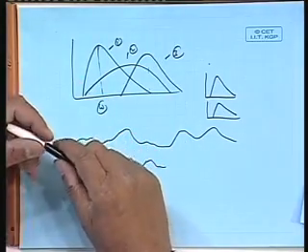If you take a particular location and wind is coming from a particular direction at a particular speed, waves will be random, but you would still expect the statistical quantity of waves to be almost the same, because supposing it is creating more long waves, you would expect more long waves tomorrow also, because of the bottom profile or some kind of bathymetry. So you would expect the same statistical distribution for the same wind speed, just that they look different. You would still expect 10 waves of 100 meters and 20 waves of 1000 meters.